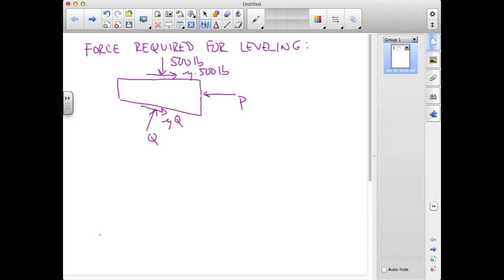So if we're treating this wedge as a particle, it only has one motion, translation. If it's slipping above, it's also slipping below, and so we have simultaneous slip on both surfaces. Because we're treating this as a particle, then we'll just have force equilibrium equations, so we'll write sum of the forces in x equals 0 and sum of the forces in y equals 0.